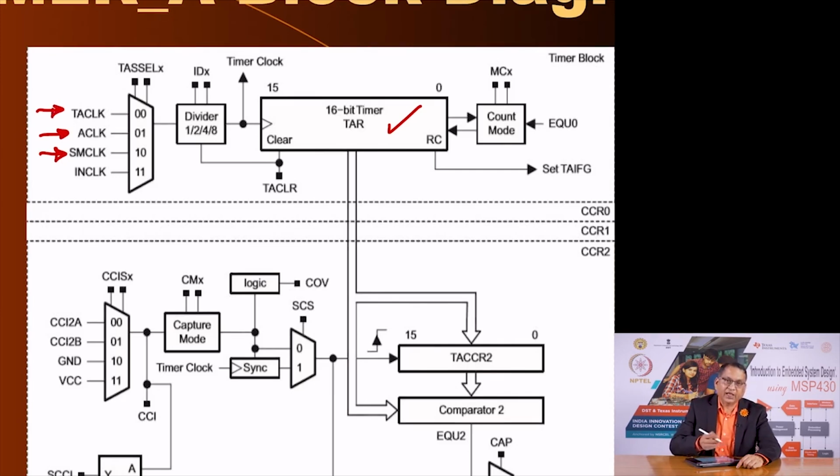That signal can be derived from a pin of the MSP430 microcontroller, which means an external signal would be clocking the timer, would be incrementing the timer, and this would effectively put the timer in a counter mode, because if we do not know the frequency of that incoming signal, all we can say is that we have counted x number of pulses from that signal. Once we select what source we want, we can also divide it with a prescaler here, and then it will be used to feed the clock for the timer.